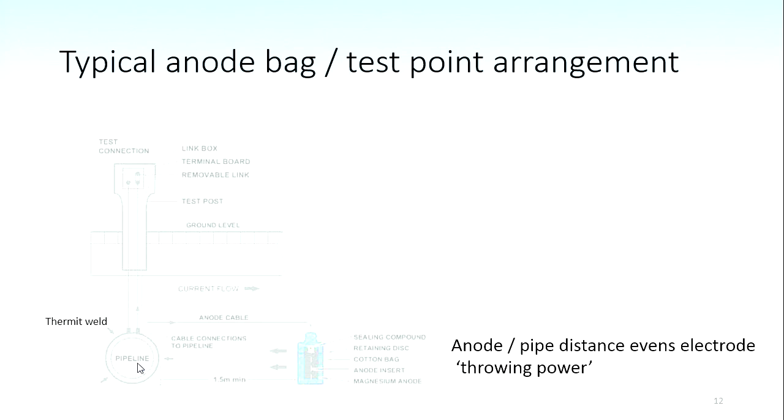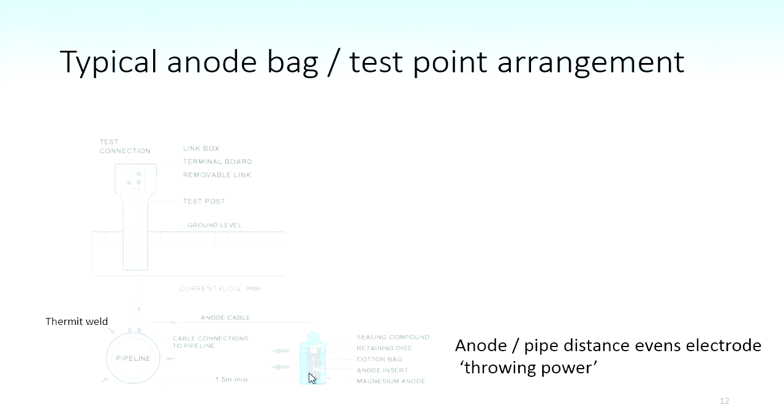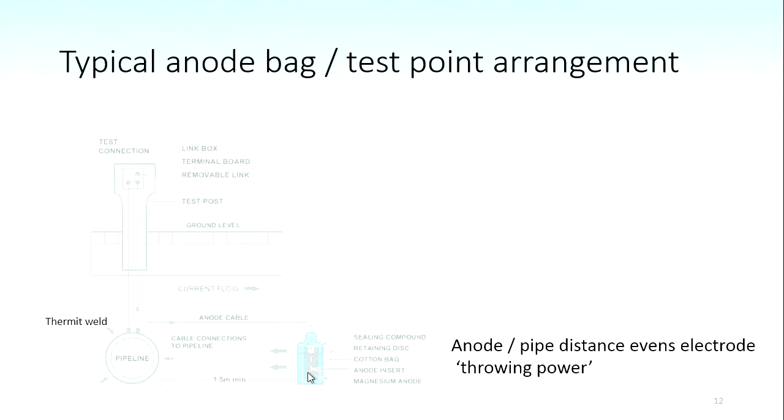That's a process where you use iron oxide and fine aluminium powder, and you ignite it, and the aluminium reduces the iron oxide to iron, generates a load of heat, and that allows you to generate molten iron, which you can pour straight onto the joint.